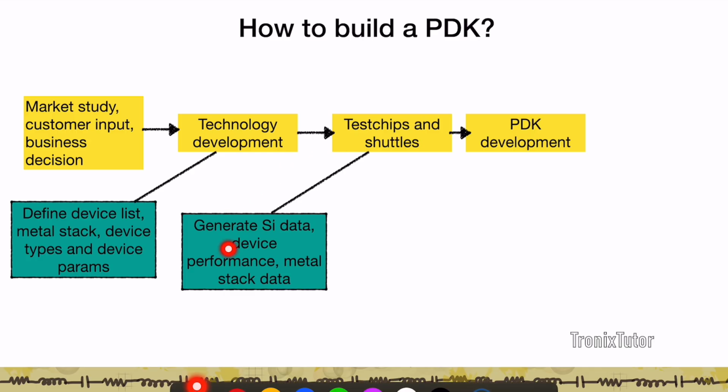After that, once all this silicon data is generated, we then next go into PDK development, right? So whenever you look at PDK, remember a good PDK ensures good first pass silicon. Therefore, a PDK has to be developed off silicon data, and this silicon data gives an idea as to what is the process that's going to run on the first silicon, right? So this PDK development essentially needs a lot of silicon data generation so as to put faith in the PDK that it is going to eventually be something that can be done repeatably and with high yield in the high volume manufacturing.